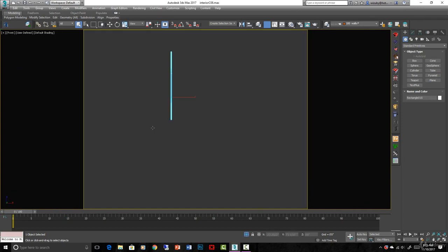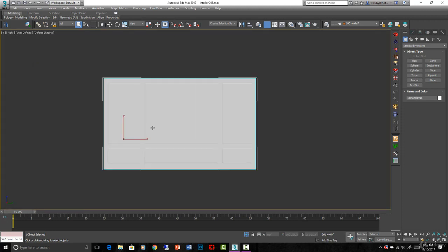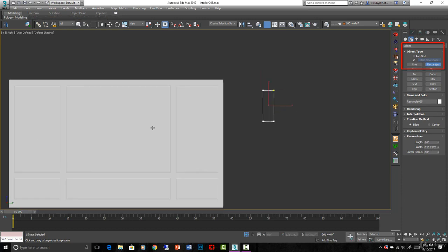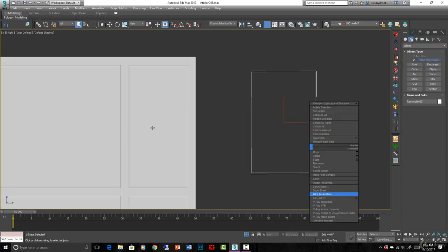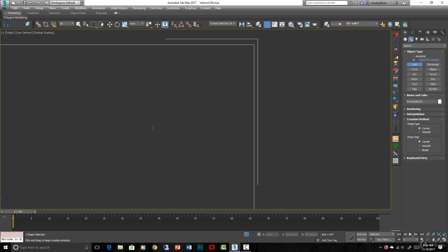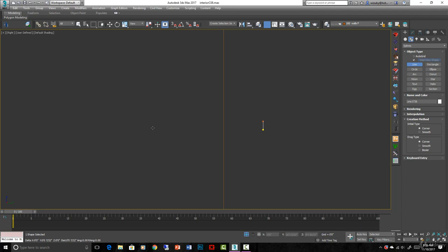These are actually very easy to model. Okay, so what I did was I took a box, or a rectangle I should say, standard primitive shapes. Go to rectangle, convert it to an edit spline by right clicking, and then I just created a basic profile like this. Something like that. Okay, and then bring this out and close it off. Close spline, yes.